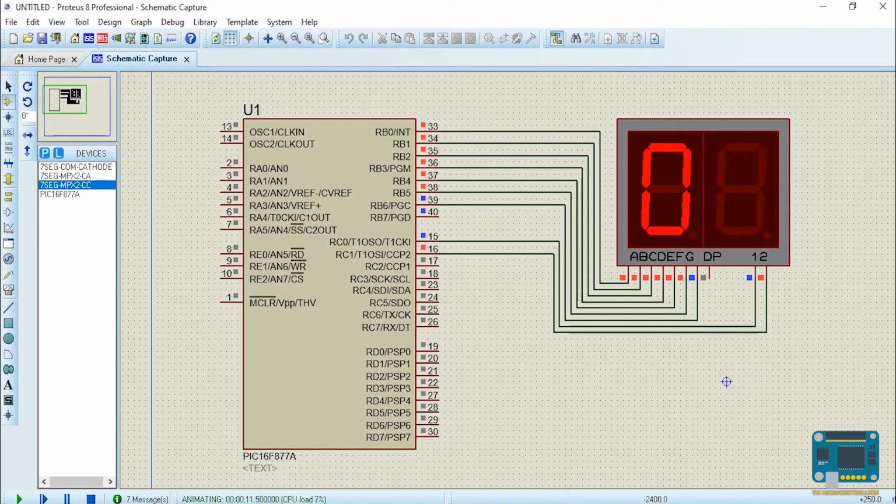And I made it so that we can actually see it flicker, just to give you the concept of the code. So what happens here is that your common cathodes, both 1 and 2, are constantly switching, right? And then depending on which digit turns on, then we throw a value for that digit.